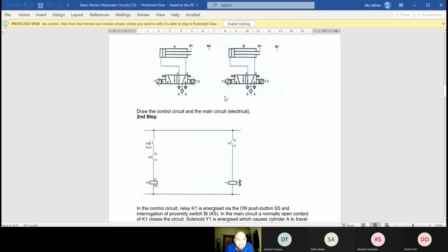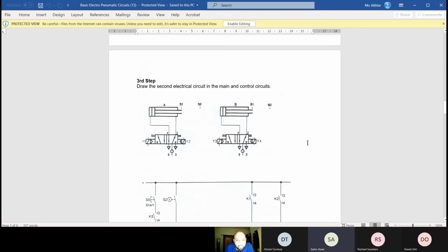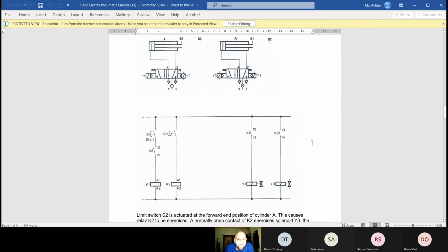Okay, but yours is going to be controlled both ways, open and closed. So you're going to have something like this, but not quite this. You're only going to be using probably one solenoid, so one actuator. So one output of the PLC would switch it on. K1, that will make this switch on.